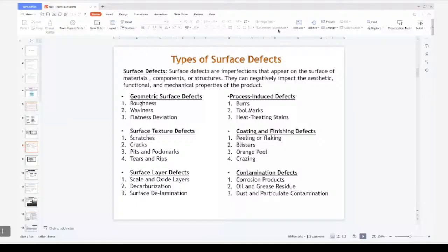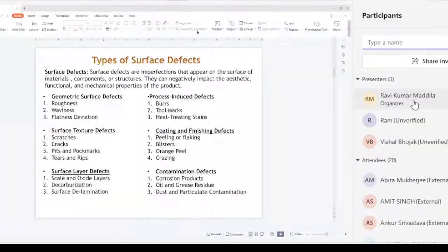These are all two-dimensional defects. And structural anomalies are not detected through NDT, like grain boundary defects, twin boundaries or columnar grain structure, because the size range is below the size range I showed you. So we don't generally look at it. Segregations are looked at mainly on castings. And residual stresses are also important.